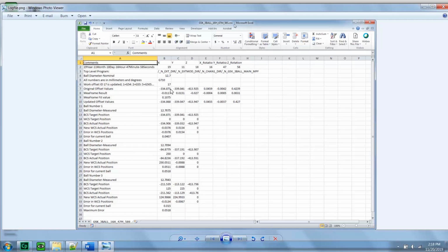So in this case, I already have about a ½ degree rotation in Z because of how I mounted the plate with my 3 balls. When I say how I mounted it, I mean poorly. So then it tells us that our correction values are going to be very, very small, which is kind of expected since I've run this several times in a row. This is more or less an error of magnitude that goes along with repeatability of the testing that I'm doing.